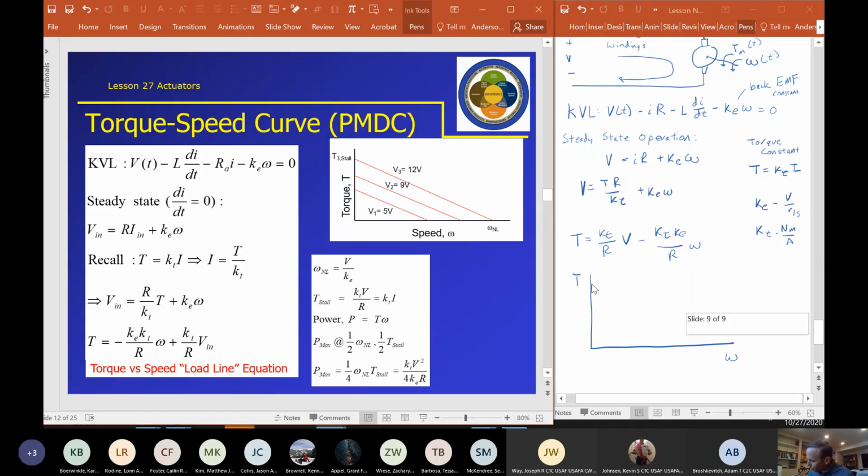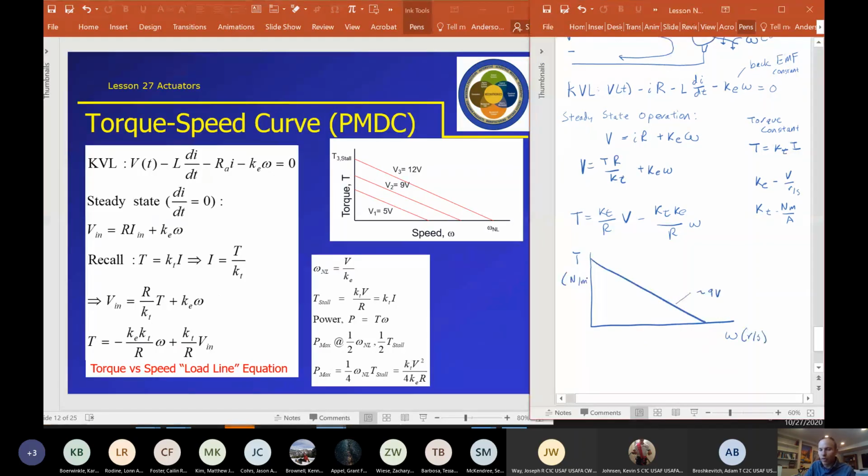What we're doing here is we're trading speed for torque. So when I just threw this motor on this battery, right now it's running at its maximum speed because there's no load being applied to the motor. Let me show you the motor. I do have this little piece of tape which is creating some drag, so that's some torque. So I could take the tape off and it might spin a little bit faster. If I put a load on the motor, it's going to slow down.